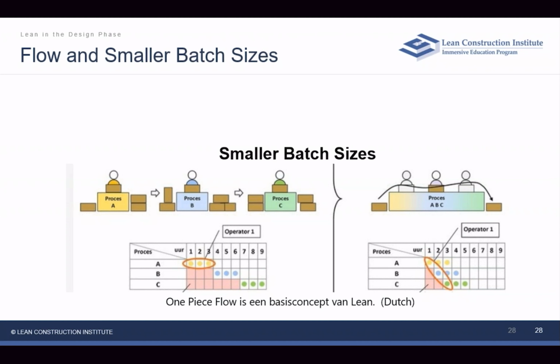I've thought about where I've seen this, where the steel supplier might supply a pre-shop drawing where they just go through their criteria, just a small batch. They go through their criteria, get approval on that, and then they dive into their shop drawings of the steel fabrication. That way they didn't do a whole bunch of work and then have to redo.